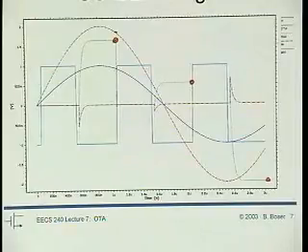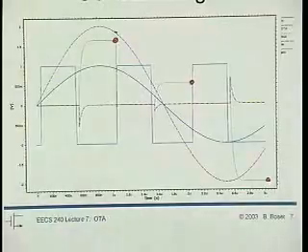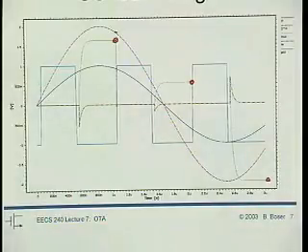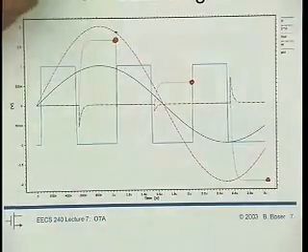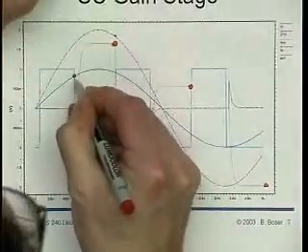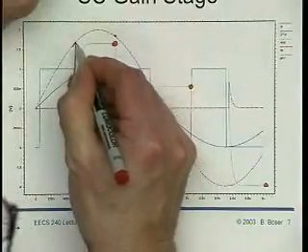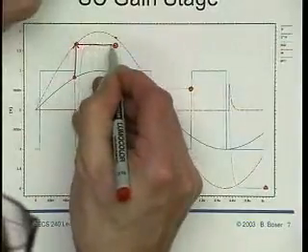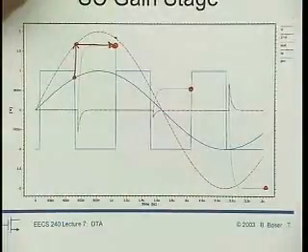What's wrong? Well, the question is, what does our amplifier really amplify? It amplifies the voltage that it samples on CS during phase 1. And particularly the sample that it gets is the value at the end of phase 1, right? That's what it takes. So it actually takes this value, multiplies it by 2, and spits the result out at the end of phase 2. And it matches like a charm.